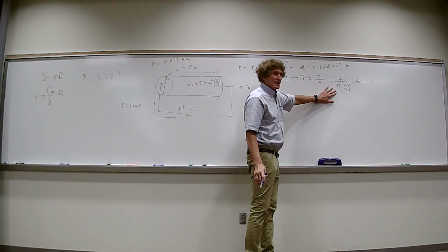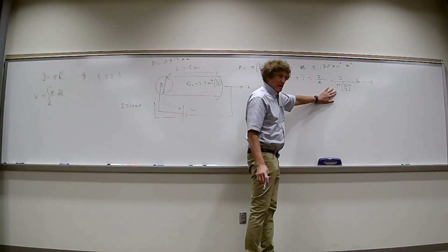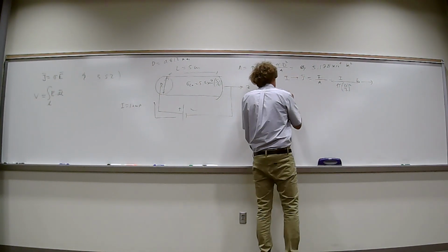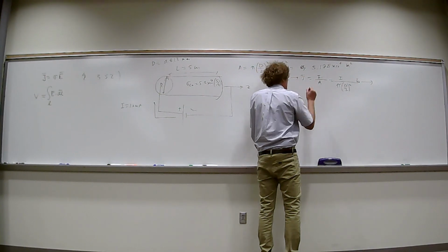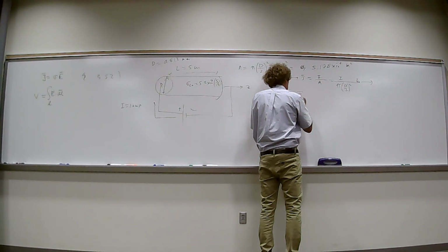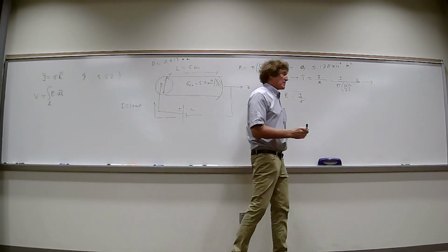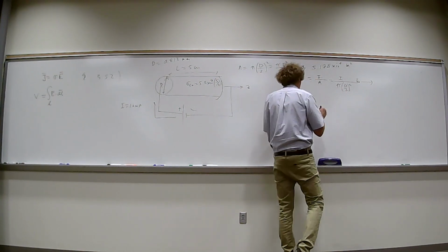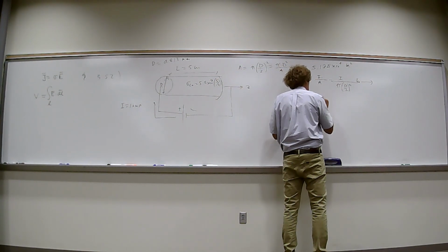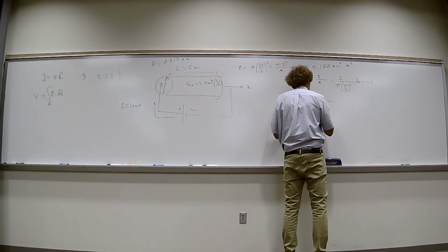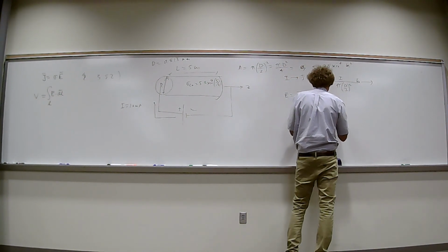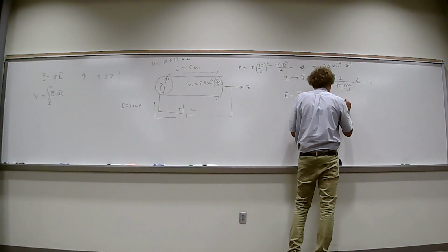I just want that calculation. All right? Now after that, what do I do? Now I get E, right? And I say that E is simply equal to J divided by what? Sigma. Y'all see it over there? Now you have the E field. That would be volts per meter. I can write it down for you. That would be I over pi d over 2 squared times sigma. It would be in the AZ direction.